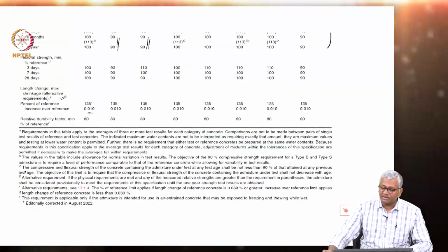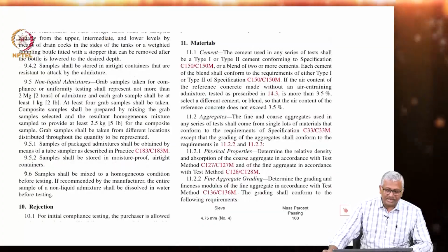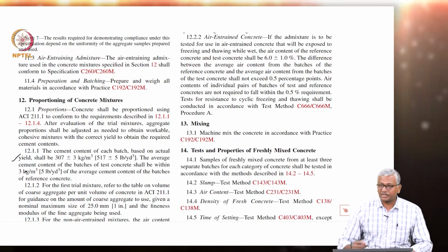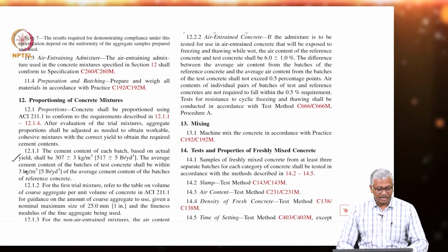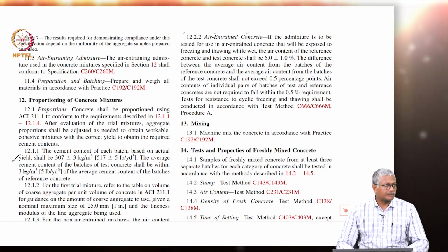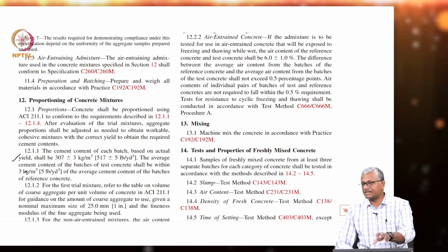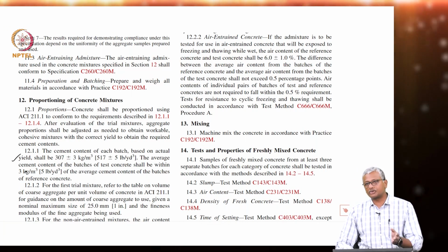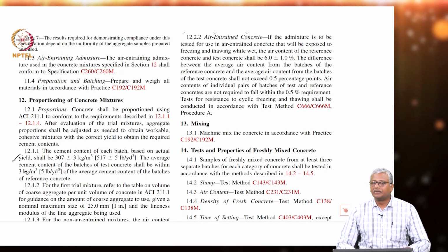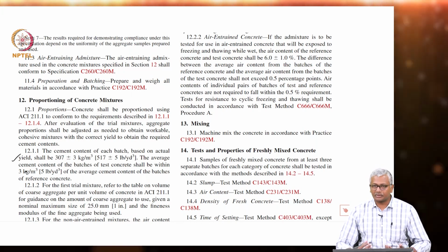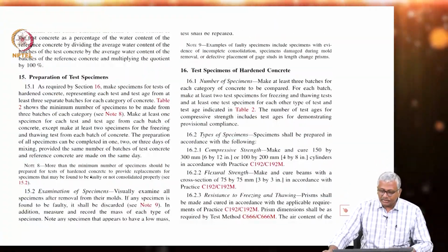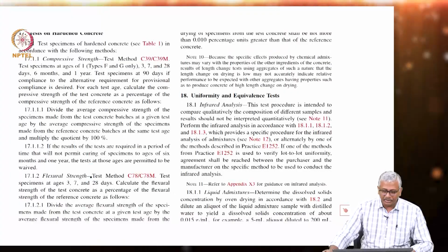So, these are the requirements given when the concrete is designed with this kind of a proportion, whatever is given here, right, with 307 plus or minus 3 kilogram per cubic meter and a water content that is sufficient to get you 100 millimeter slump. Okay. This is a standard test done for the specification. For your job site requirement, you may have obviously other mix designs. Your cement content and water binder ratio will depend on the strength and other performances that you desire for your concrete.